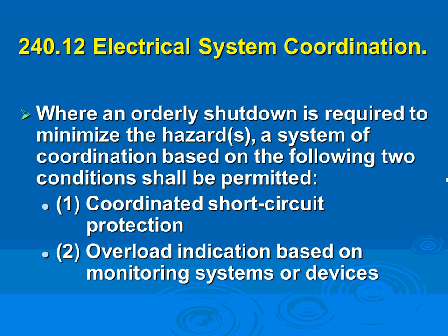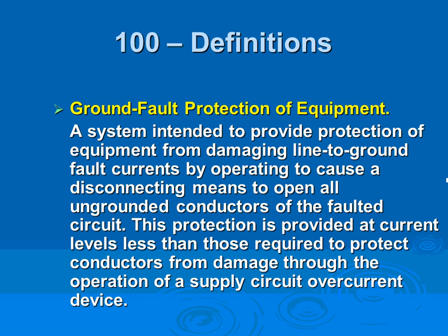The emergency system requires coordination. All your lighting for emergency systems, fire pumps, and elevators used for emergency must be coordinated. Other than that, to minimize the hazard, legally required emergency systems and legally required standby systems require it. Other than that, it's optional to do the coordination.